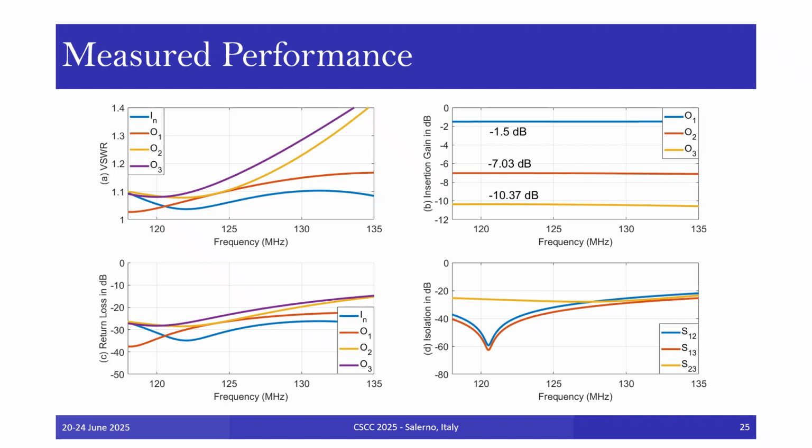The differences noted from the simulation results can be attributed to any uncompensated parasitics of the passive components and to the actual values of the isolation resistors employed in the design, which were slightly different from those given by the derived equations. The simulation results presented in the previous slides were obtained with ideal passive components, and thus the simulated power splitter features a sharp and narrow band response around 1 to 1.5 MHz.